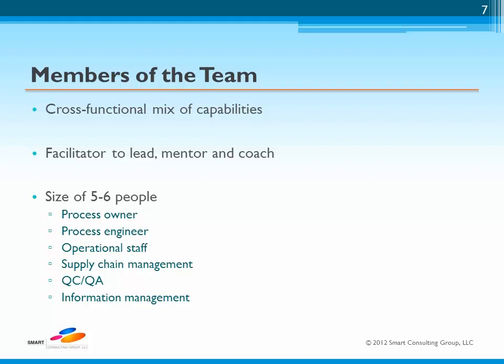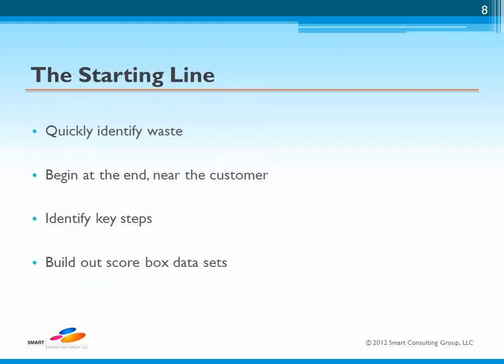The best way to properly evaluate how a process runs is to observe the process live and, where convenient, to videotape the key steps. Experience teaches that a live recording of what actually happens as the process is operated provides a truly honest representation of how things really run, and not how they are supposed to run or operate per some engineering flowchart. This is often referred to as doing a Gemba walk, where one goes out to the point of activity and observes things firsthand.